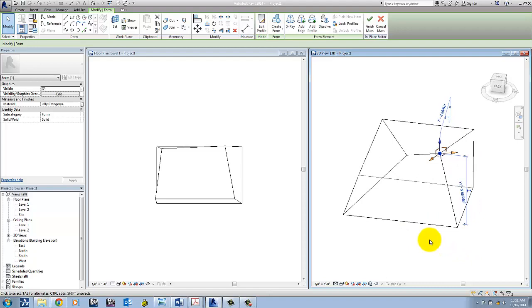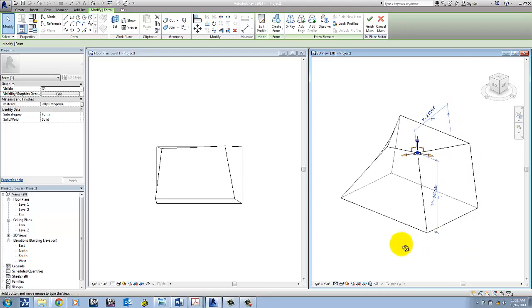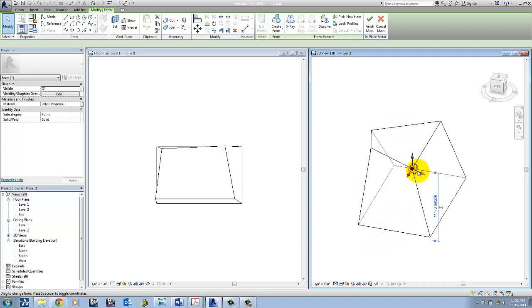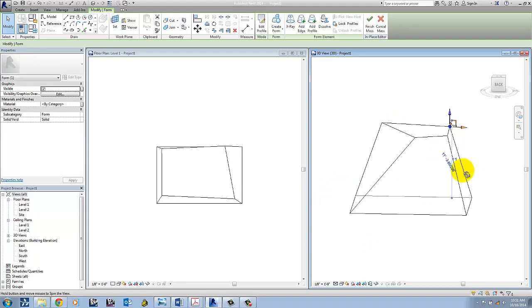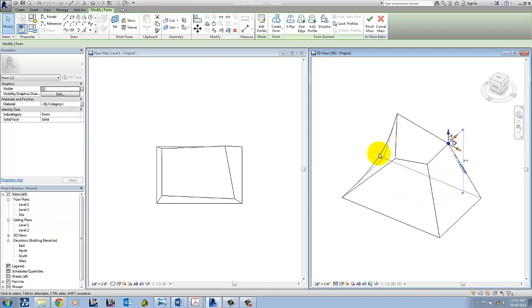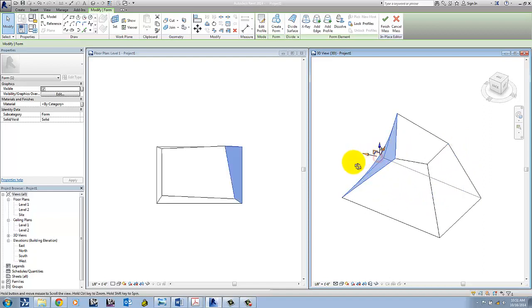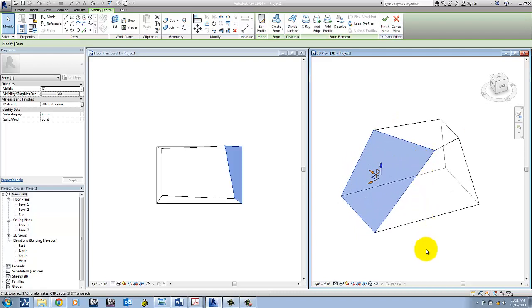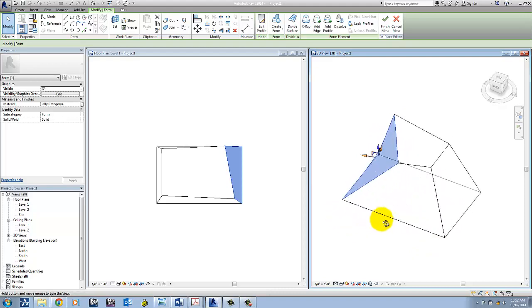So you notice with massing, as I start grabbing these points on this extrusion, I'm essentially just massaging or molding this extrusion to get the form I want. But you'll notice as I start moving this thing, the faces, these surfaces, are really becoming molded and meshed. They're not breaking, or you don't create these staggered lines like you would if we were editing the face of a flat floor. Whenever you add a point and you start pulling it, it'll just start breaking it into flat surfaces, multiple flat surfaces, in order to get that shape. Here, you actually get the nice curved meshed surface.